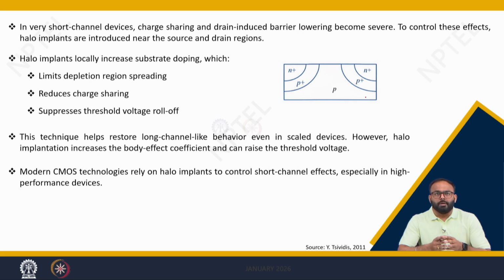Halo implants means locally increasing the substrate doping, which limits the depletion region spreading, which reduces the charge sharing and suppresses the threshold voltage roll off in small channel devices. Now, modern CMOS technologies rely on halo implants to control the short channel effects, especially in high performance devices. Strictly speaking, the modeling of the charge sharing effect is essentially required when there are no halo implants, because halo implants do not provide that much short channel effect. We need to model and consider charge sharing.